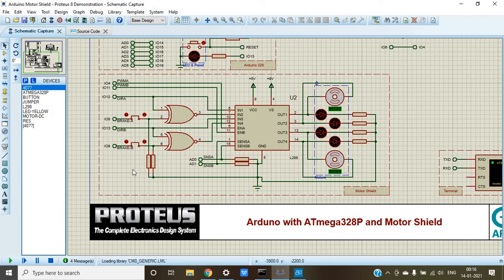So first we start off. As we can see, the motor has started rotating with a steady increase in the RPM. This value will increase till it reaches a certain value. As we can see, the value has reached its peak, which is 35, and this is the RPM that we get for PWM 200. So we stop the simulation.